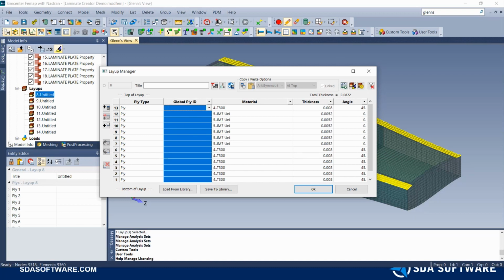And then another question was, does this new Layup Builder work to get layer data and ply drop regions from FiberSim? It does. And if there's enough interest, we might do a separate webinar on those capabilities. But it does for sure. Femap has spent the time to make sure that it can read a bunch of information from FiberSim and pull that in and generate all the layups. So that's definitely something worth reading more about in the What's New documentation, because there is a lot of extra capability there that I just haven't covered today.